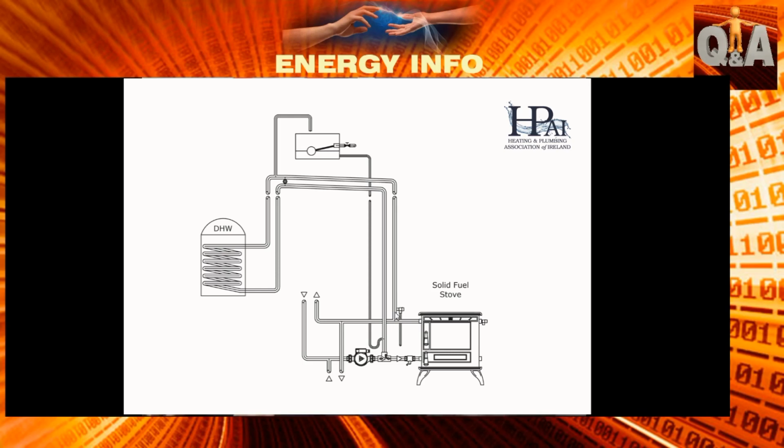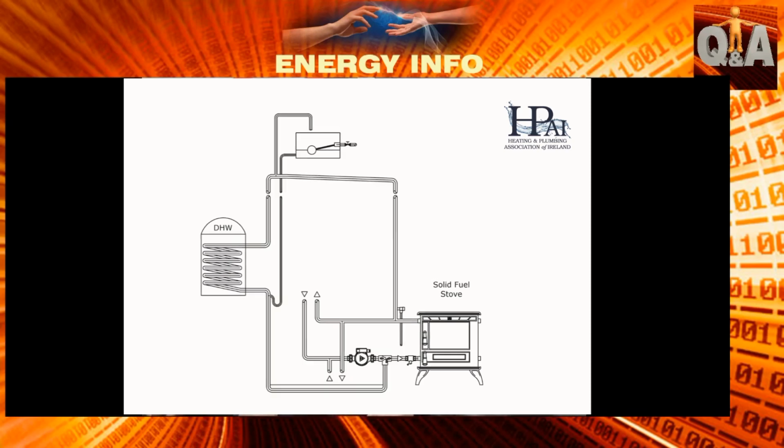This is probably the most typical system, and there's a problem with it really. When you take a flow from a stove or a back boiler and you rise up and go down to heat the coil, it heats perfectly well, falls back down across the floor and up into the stove through an injector tee again. But the problem is when the stove goes cold, the cylinder water can reverse back up, go up through the same pipe and lose heat in the attic.